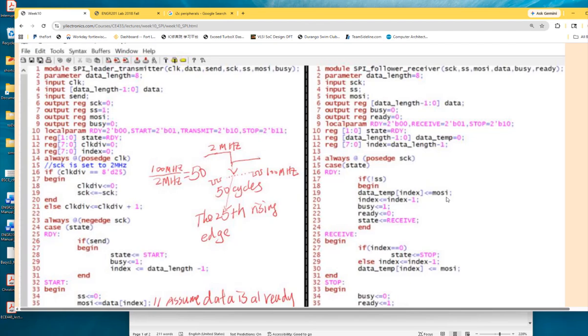Like a finite state machine? It has to be a combinational logic. I want to hear one name of that combinational logic. A decoder. Right? Your microcontroller will send, if you have like 20 peripherals, how many bits of the decoder of the code do you need? Would you need 5? 4 will give you 16, right? So 5 will give you 32 combinations, can definitely handle 20 devices.